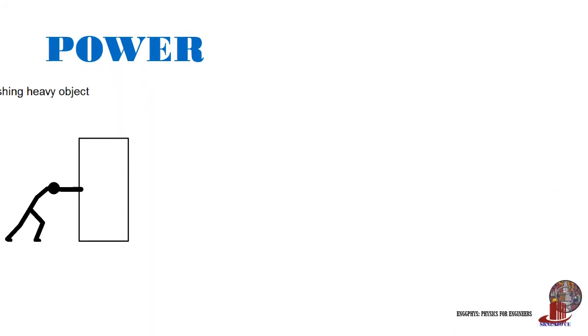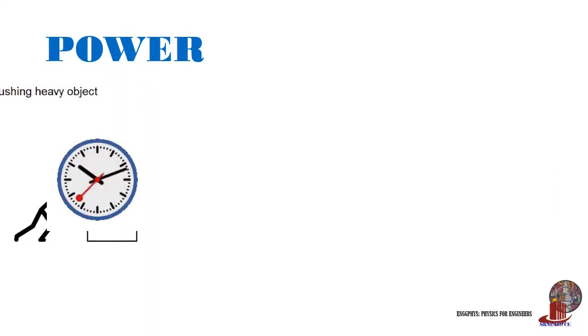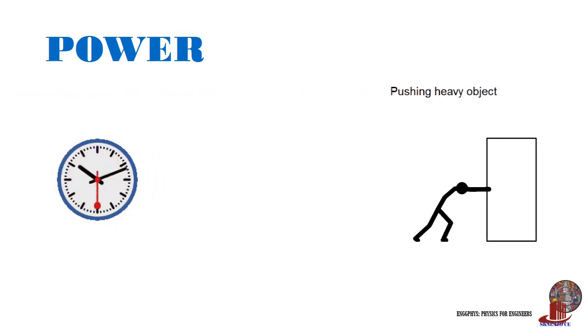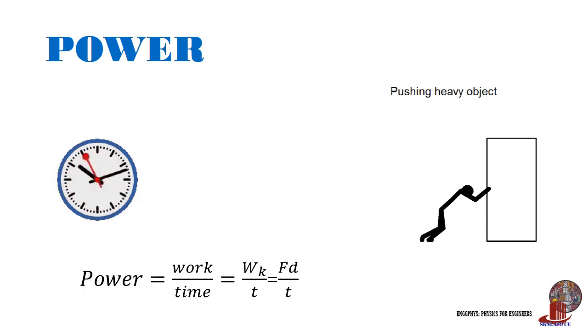The next parameter is power. Power is simply defined as the amount of work done at a specified time, so the formula is work all over time, or force times distance all over time. We all know that d over t is also velocity, so we can transform power in terms of velocity as force times velocity. In SI units, power is taken as watts, and in the imperial unit system, it is pounds-foot per second. When converting, you can say 1 horsepower is 746 watts or 550 pounds-foot per second.